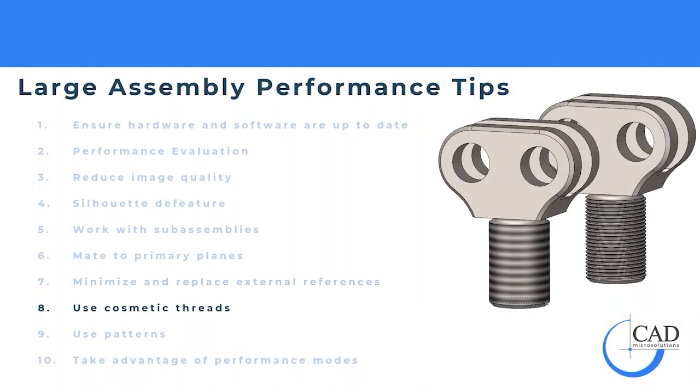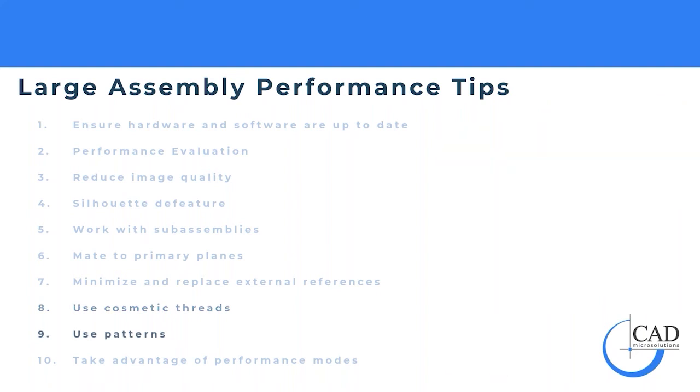Big thing here, I know we all got really excited when SOLIDWORKS came out with their thread tool so that you could cut or extrude threads, but that's not great for large assembly performance. Those threads have a ton of graphics triangles. So where possible, use cosmetic threads.